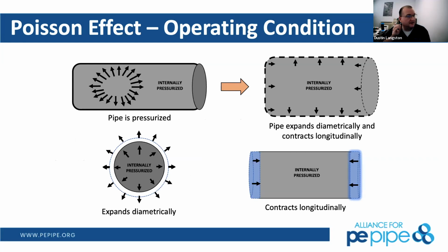for example, of the polyethylene pipe. My favorite example of this is directionally drilling HDPE pipe under a roadway or under a river, and then transitioning back to maybe a ductile iron or PVC or something like that after the drill string. If you were to just purely insert the HDPE pipe into the bell of a ductile iron pipe, once you pressurize the polyethylene, it could shorten enough to pull out of that bell. And so it becomes very important for the ends of the drill string to restrain those transitions.